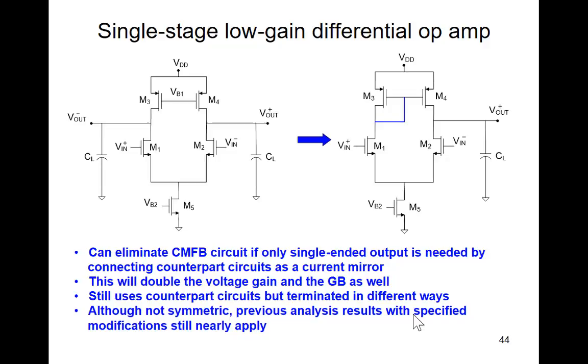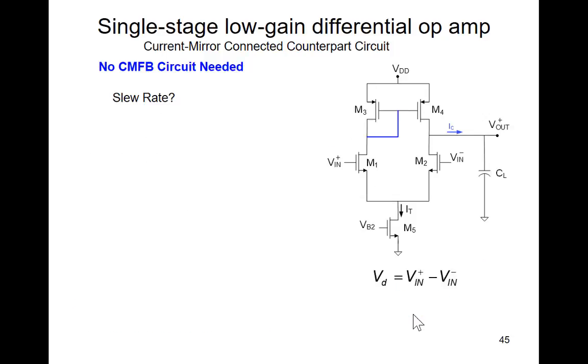I don't understand why. If you're building an op-amp for an integrated application, giving up this output is often a big deal. Because almost all linear circuits that are built on silicon will be fully differential. That means you probably got to go put the common-mode feedback circuit in to generate the bias points. How about the slew rate?